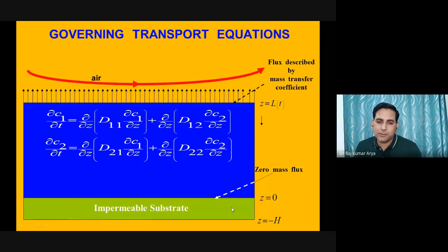Now, let's say we have the solvent, and we are talking about the example of a ternary system. What do we have in a ternary system? We have one polymer and two solvents, or you can have two polymers and one solvent. In this case, we have taken one polymer and two solvents. An actual paint will have more than 100 components. So for the simulation study, you have to quantify the solid percentage, practically 30 to 40%. The rest of the things are treated as solvents, some in a high percentage, like the base thinner. Pigments and all of this are counted as solid materials.